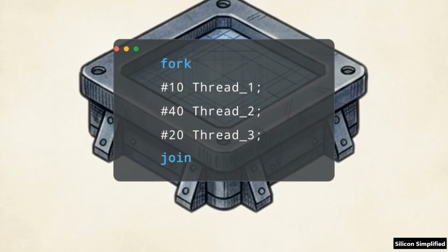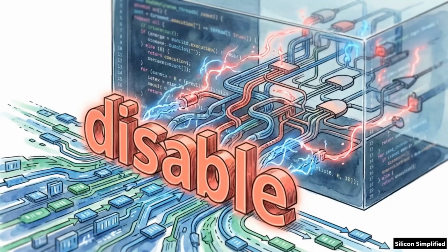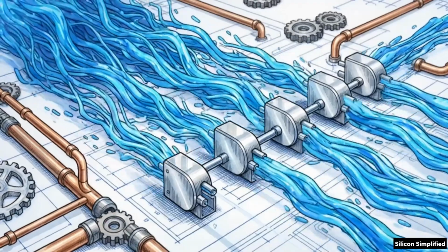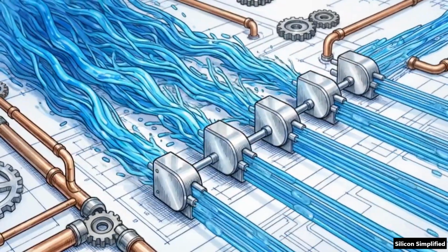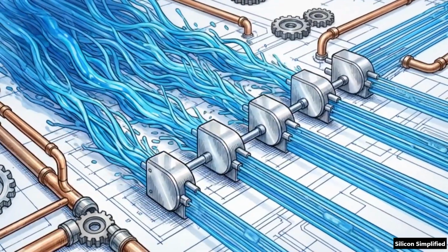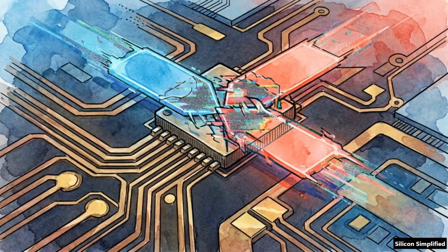By contrast, a parallel block uses fork and join. All statements initiate simultaneously, exiting only when the longest operation finishes. Verilog allows advanced dynamic control using the disable statement. Upon a system reset, you can command the simulator to instantly abort a named block mid-execution. Timing controls and block statements provide the precise routing logic needed to take wild concurrent hardware models and tame them into reliable, deterministic systems.